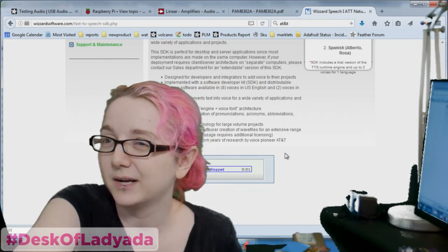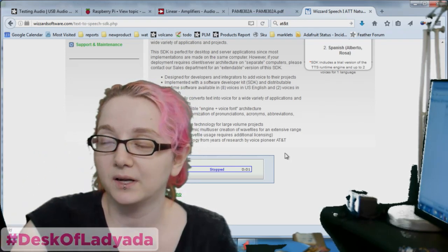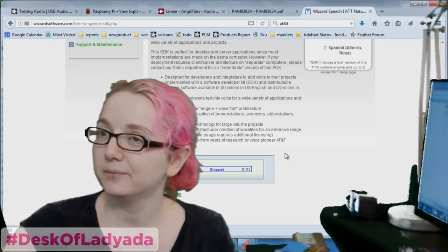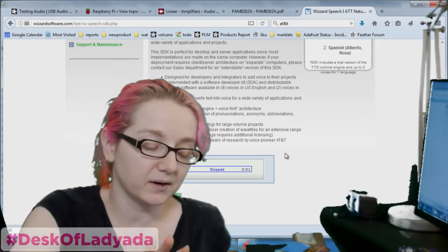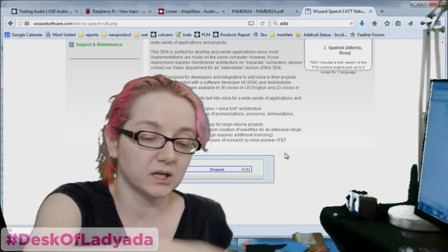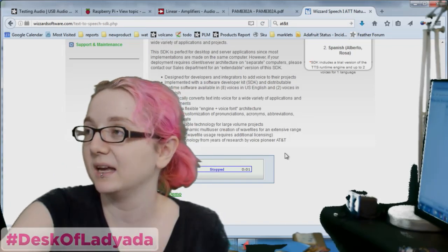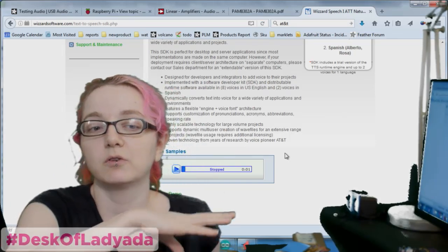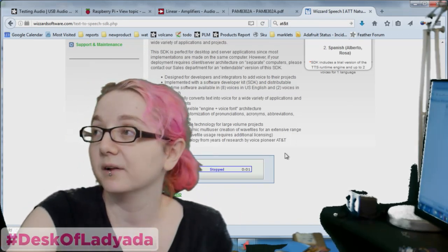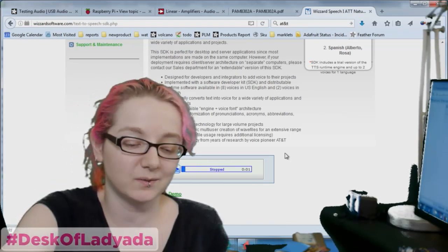But right now, I tried it with the 32U4 to play the Talkie library, and the square waves made it way too distorted. But I'll probably do that next. Again, I'm not expecting to get an audio file, but I'll probably generate some text to speech, get it on here, and then just play it on the iPod until I feel like I have the settings and the gain, everything right, and then I can use the Circuit Playground analog output to play files, basically. It's going to take a couple steps. I have to write some code to do that. So that's why testing with an iPod is a lot easier.